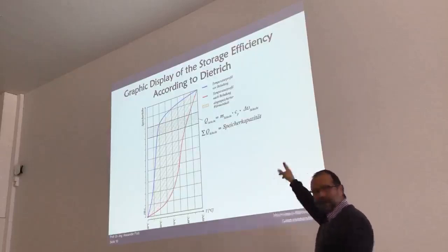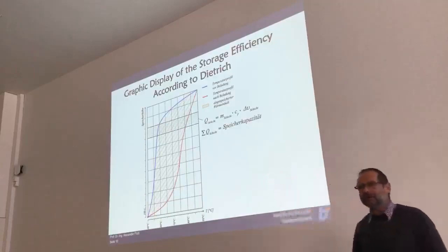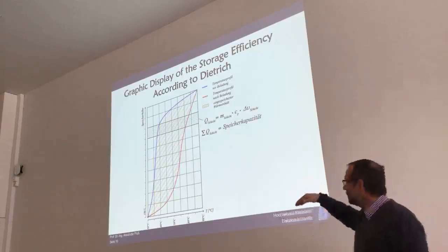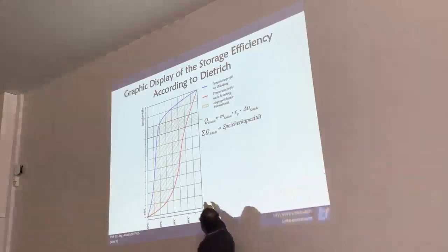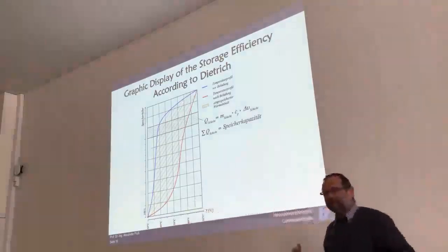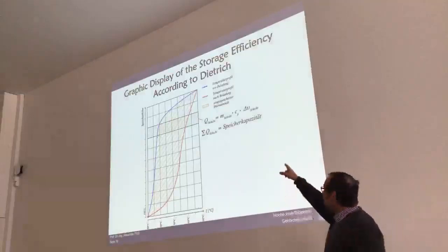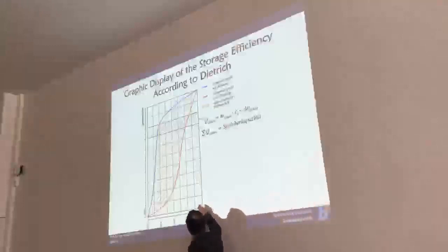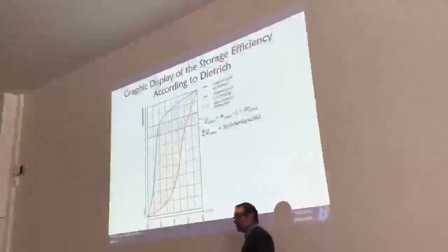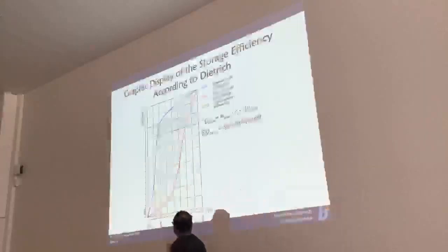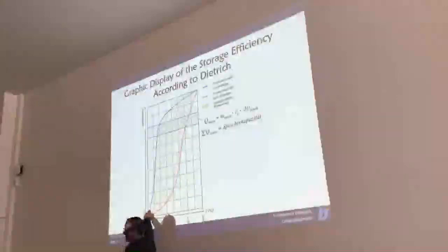Here we have 10 layers. We talked about before that the tank has a capacity of 1,000 liters, so in that case, every layer has a capacity of 100 liters. If you are now calculating the specific capacity of each layer, it's the mass of each layer multiplied with the specific heat capacity of the water, multiplied with the temperature difference of the layer from the point when the generator is switched on and the generator is switched off.